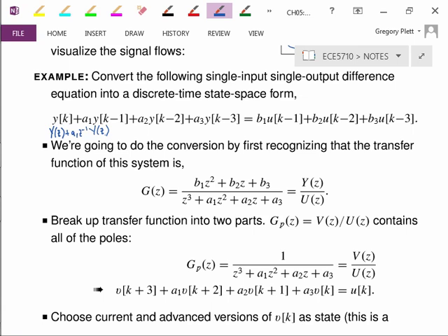And if you're really up to speed on your z transforms, you'll say, but wait a minute, there's also an additional factor that has to do with the initial output of the system, the initial value of that signal. But whenever we're finding transfer functions, and this is critical, we assume that the initial conditions are 0. So I don't need to worry about that, and that's simply because I'm finding a transfer function.